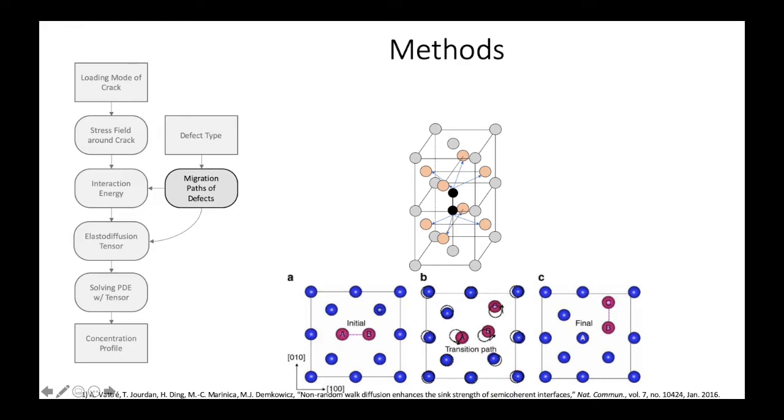For self-interstitial atoms, the dumbbell shape makes migration more difficult. For one, there are three possible orientations for these structures, with the axis pointing in the 001, 010, and 100 directions. And two, due to the dumbbell structure, the dumbbell can only migrate in a certain direction that is much more restrictive. Due to this, there are a total of 24 migration paths for the SIAs, 8 for each orientation.